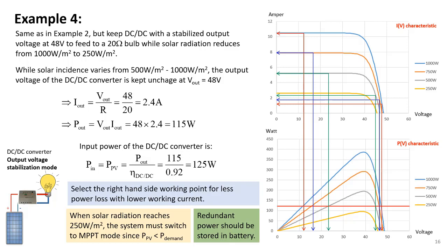For the analysis in this example, we can see that the use of battery is a must in PV systems in order to utilize the most power from the sun, or else the redundant amount of electricity will be wasted away. On the other hand, the battery is sometimes charged and sometimes discharged to feed the load. Thus, it requires a bi-directional switching system.